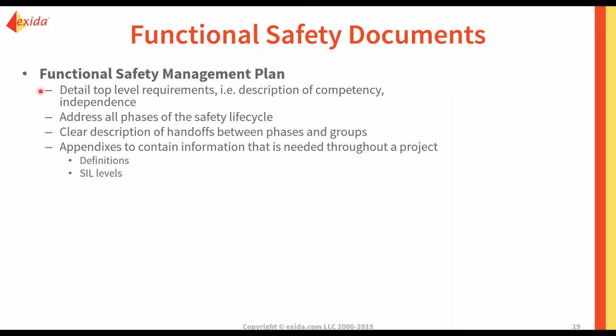So providing those overall top-level requirements that then are applied to each individual process. It addresses all phases of the safety life cycle. So really, it just provides the high-level approach of the organization. So it'll include what is done in the analysis phase, so the requirements for going through and doing a process hazard and risk assessment. What's done for documenting the safety requirement specification, and then all the way through the design, so the SIL verification, factory acceptance testing, implementation, and also then even to the operations and maintenance phase.